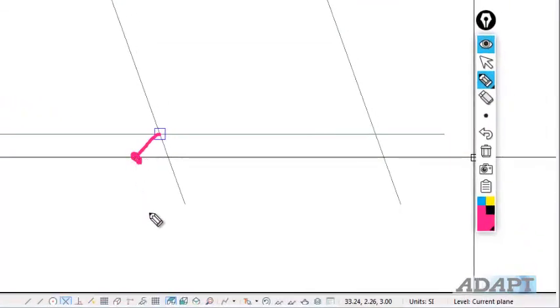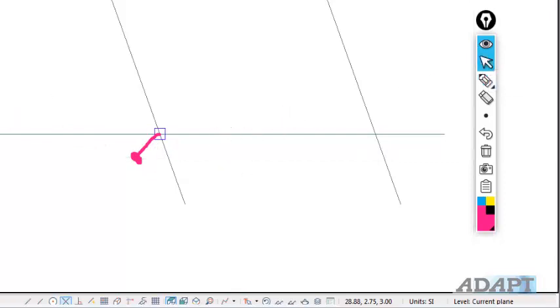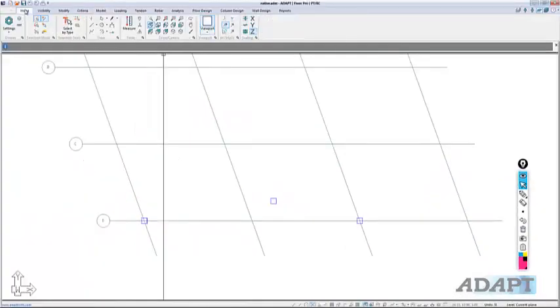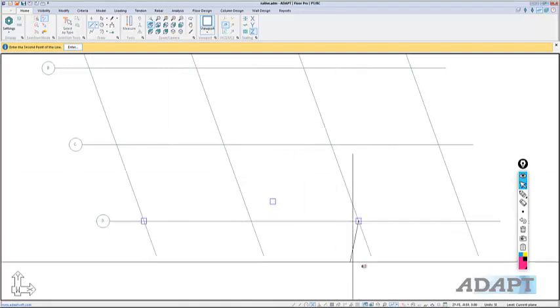Because I don't have a reference point to just easily snap that column to, I have to create a reference marker or an intersection. Okay, and this obviously is more difficult than doing it this way, but this demonstrates how you might use reference lines in the program. So we'll go to Home. I'll go to the Draw panel and just create a reference line.